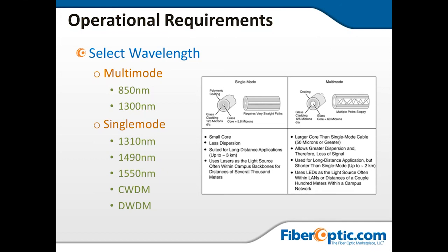You can go everything from coarse wavelength division multiplexing, which is up to about 20 channels or 40 channels with a 20 nanometer spacing, up to DWDM, which I've seen some designs with over 100 channels, over 100 discrete lambdas, running between 1550 and 1675, and just packing them in there every 0.8 nanometer. And now those are higher cost lasers. The CWDM will work with your baseline kind of lasers in most applications, and there's a lower cost.